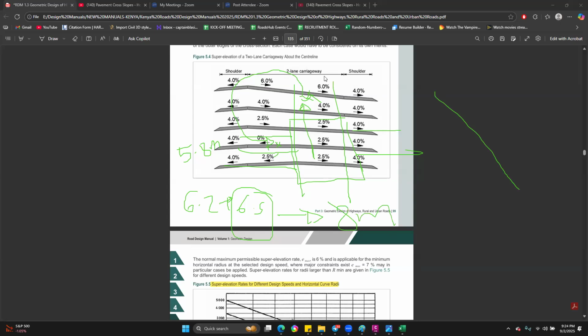So if you want to move from that 8 meters to 0 meters down here, and this length is a bit small, the super elevation should be quite high, around 8%, for you to navigate that loop quite fast and safely. Okay. Thank you. You're welcome.